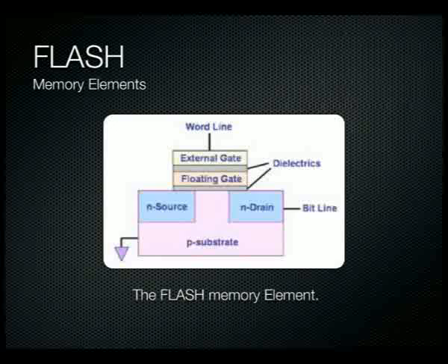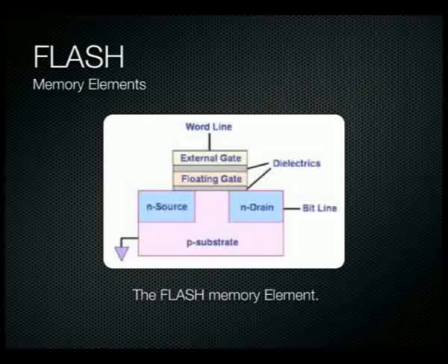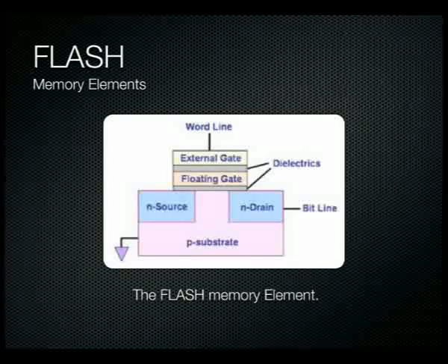What will generally happen is you'll be writing into a bit of RAM that's on your flash drive. Generally you have at least 512 bytes of RAM to represent the block that you're about to write, and you simply write the bytes in there. If you don't fill up that 512 bytes, it will go to whichever page you're going to overwrite, grab what's left of that page, load it into that RAM, and then write that entire 512 bytes at one time into the flash drive.